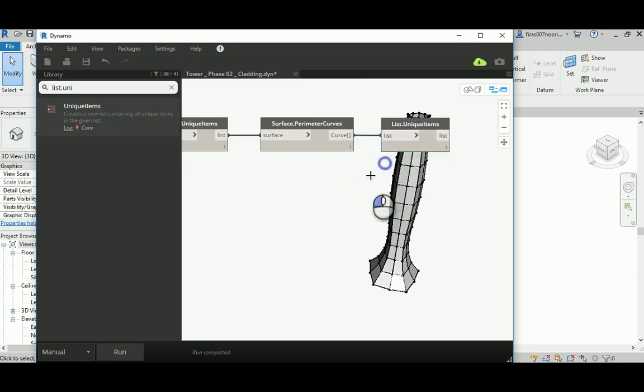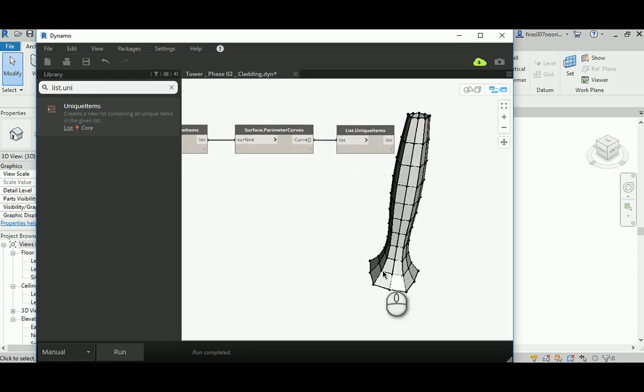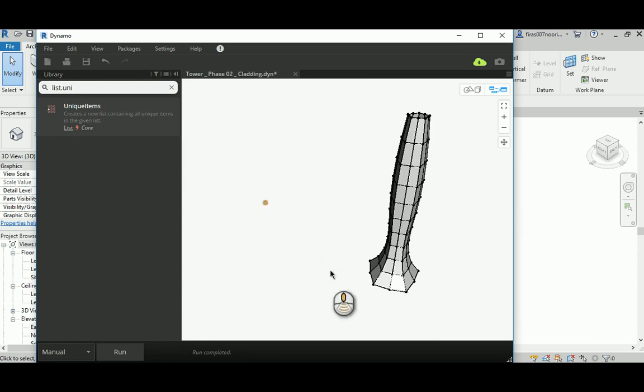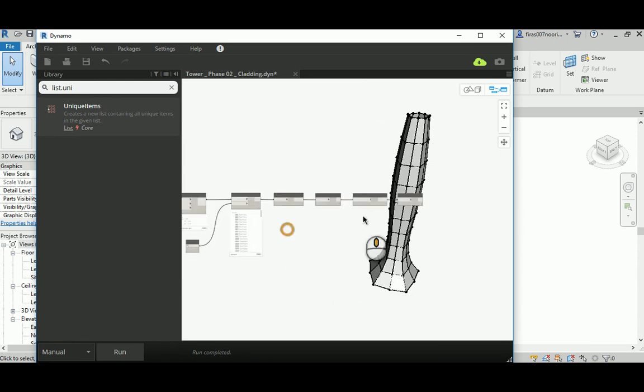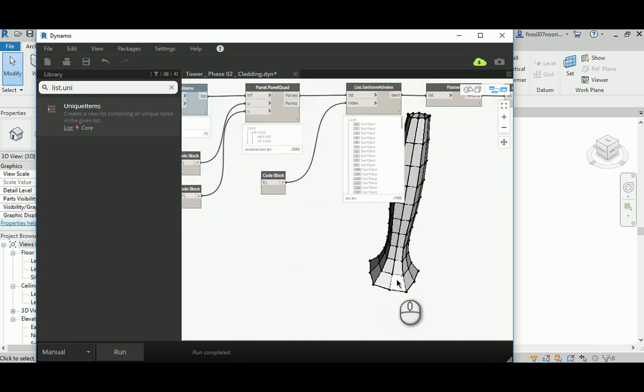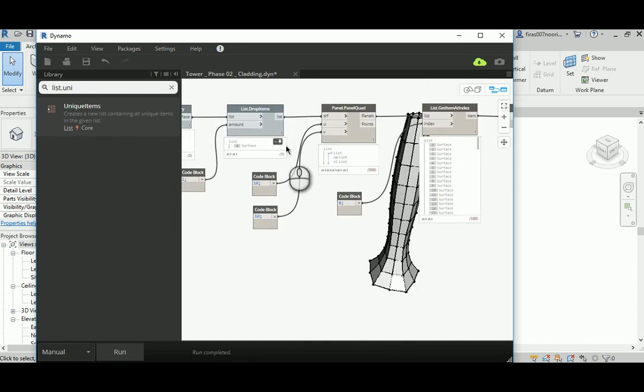Now, we know the points, we know the panels. You can go ahead and change things a little if you don't like it. Probably it's not really curved enough. So I'll go to U, probably make them 15, and run that again. Remember, the higher the number you go with, the slower the process, and usually it's going to be really painful.